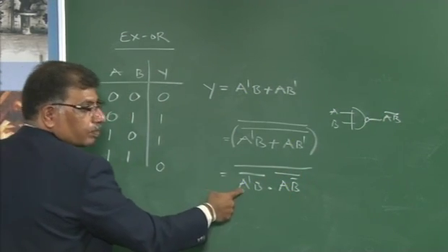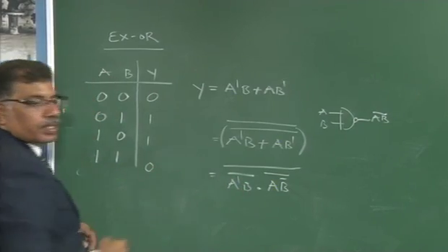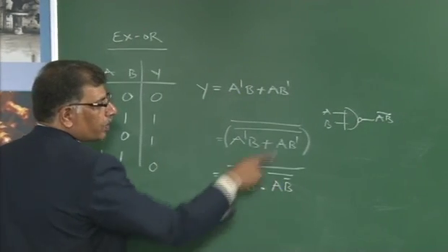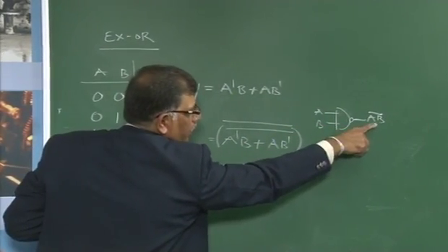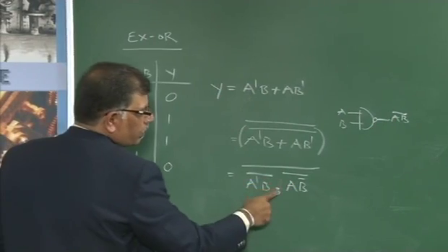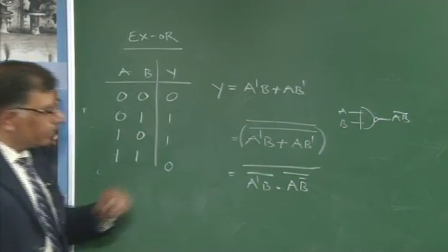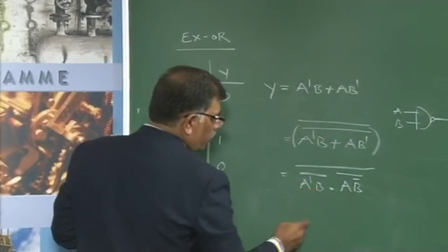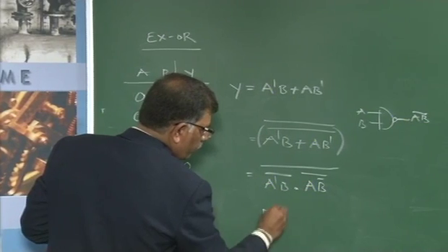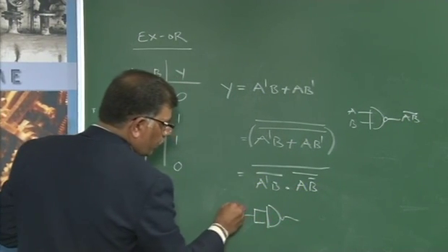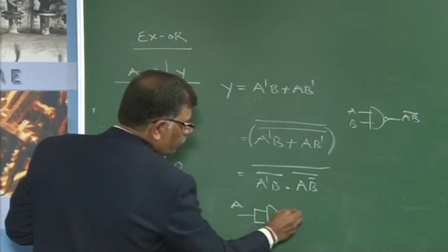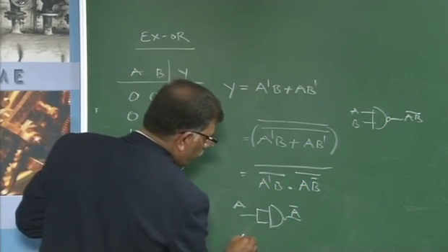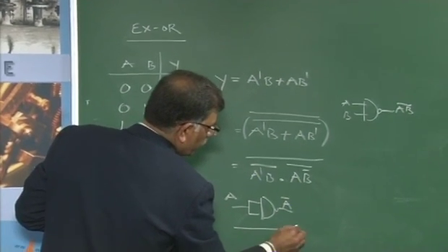I will not simplify this because you already have product terms between the logical variables. Between the logical variables you should not simplify it, because the expression with respect to a NAND gate is a product term. So I will keep it in this form and then realize it by using NAND gates. First I take a NAND gate and short the input terminals, like this A, and the output that I will be getting is A bar.